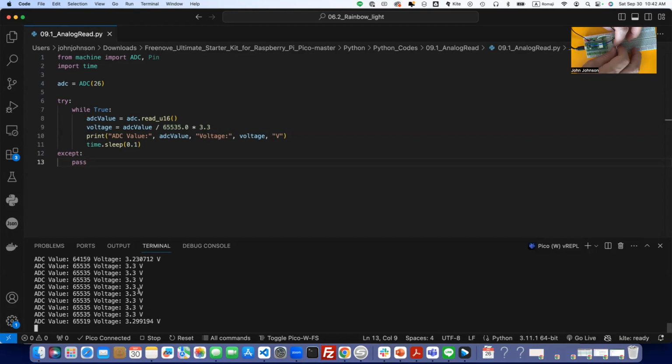So anyhow, I hope you've enjoyed this. This is a potentiometer, and it's a lot of fun to play with things like these and see how you connect and get signals that take things from the real world, which is analog, and convert them into things that we can understand in the digital world. Right now we're doing a potentiometer. We can get readings for temperature sensors, for gas sensors and things like that that are going to give us an analog reading, and we can translate that using the ADC into some type of digital information that makes sense to us.